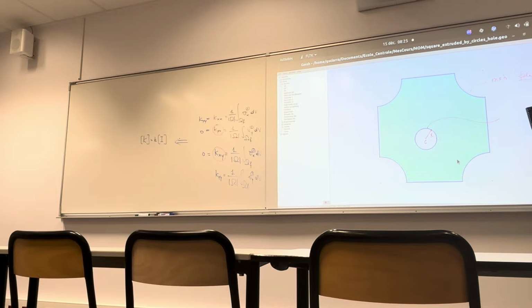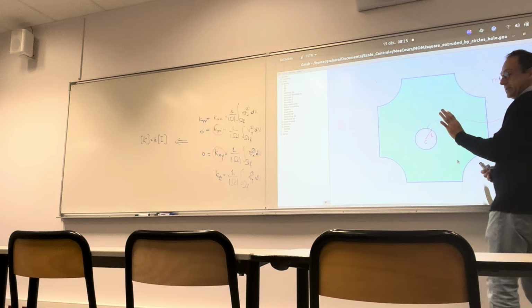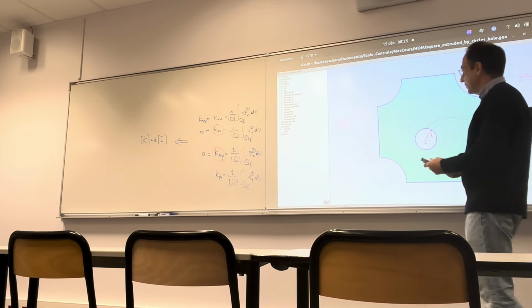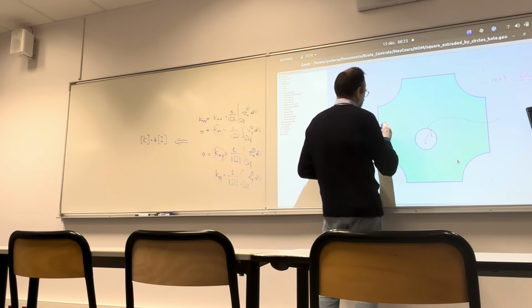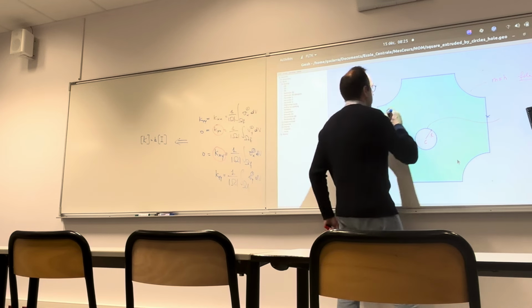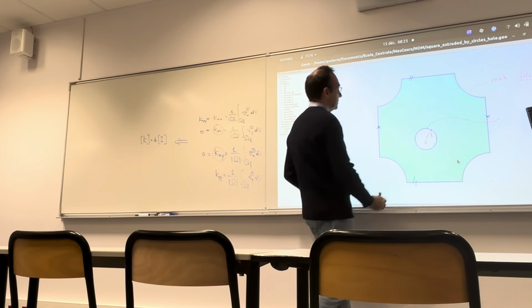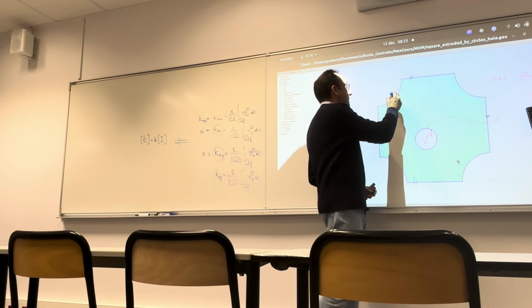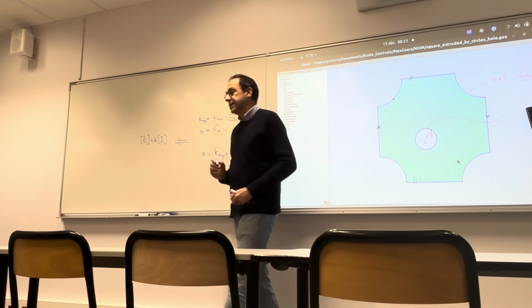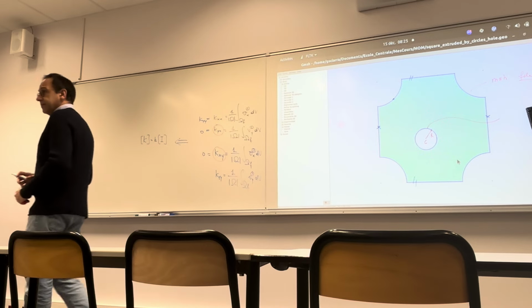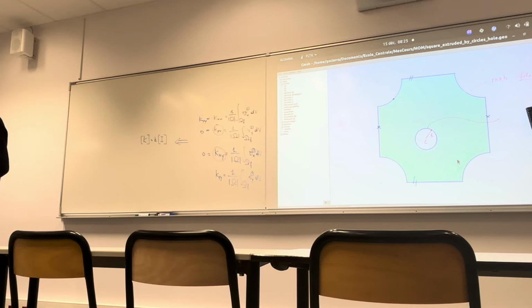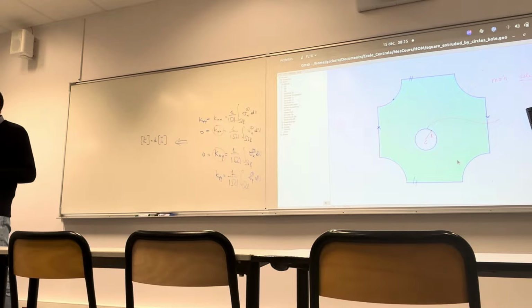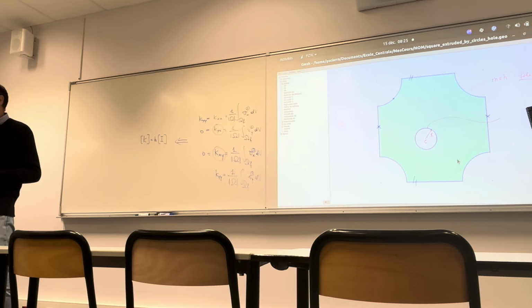According to your understanding, our problem is still the Stokes problem, no? So for the Stokes problem, I remind you that on the external part of the boundary we assign periodic boundary conditions. For instance, the velocity there is the same as here, and here what did we assign? Velocity equals 0. Which was the standard condition that we have when there is a flow on a wall.